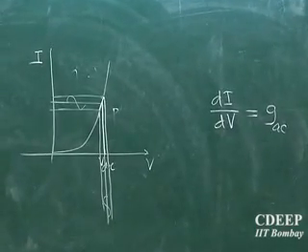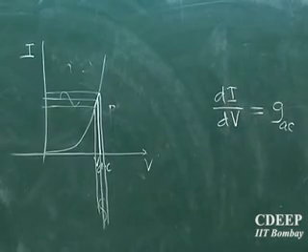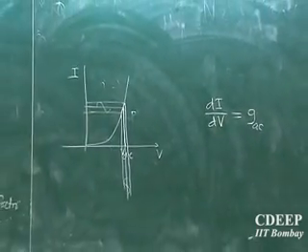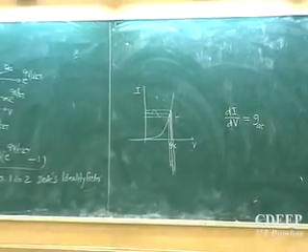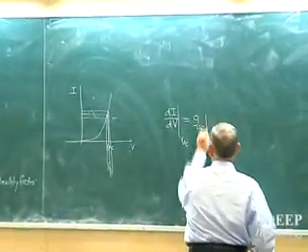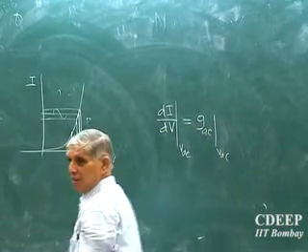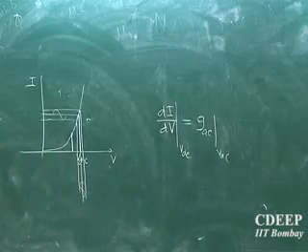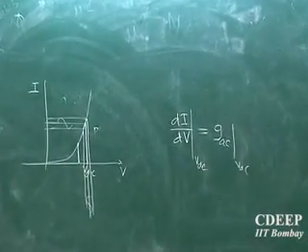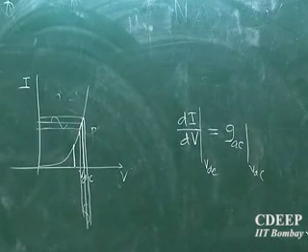What will the DC conductance be? I by V. Is that correct? But what is the AC conductance? di by dV, the slope there. But it is a function of at what voltage I apply, because at some other point, this will be different. Is that correct? So where I bias the diode has relevance to the value of R we get.